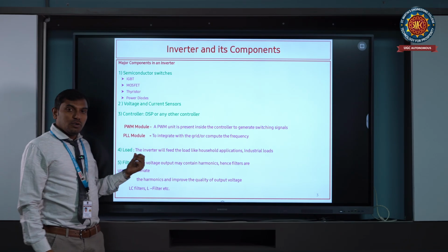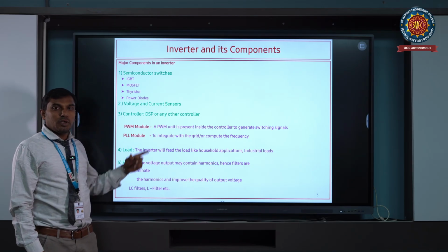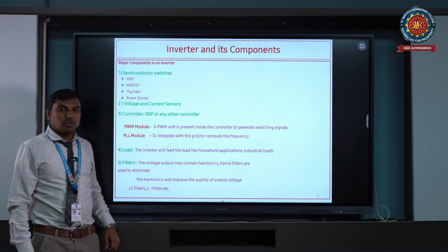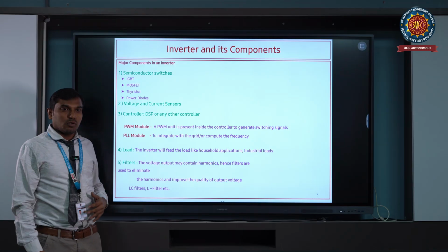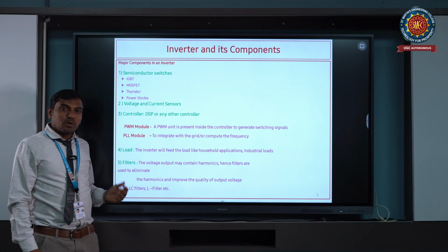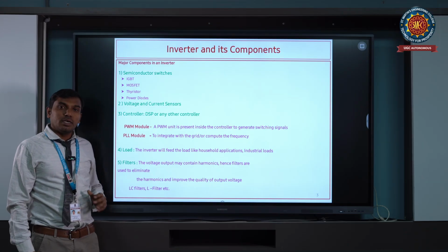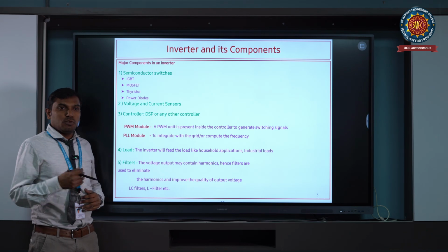And then we need to find what type of load we are connecting. Therefore, load is an important parameter of the inverter. And then we have filters. Filters are used to eliminate the harmonics which are generated by the inverter. So the purpose of the inverter is what I told: to generate an AC waveform, but sometimes a pure AC cannot be obtained using a static inverter. Therefore, we need to use filters to